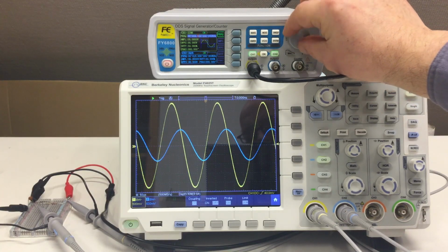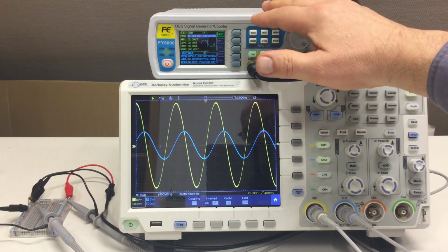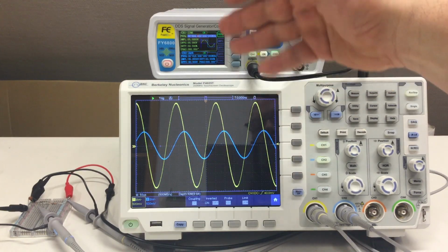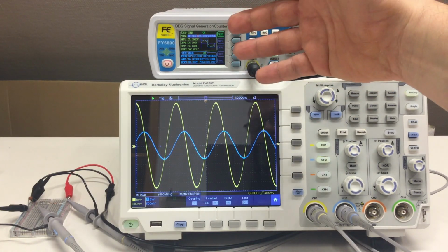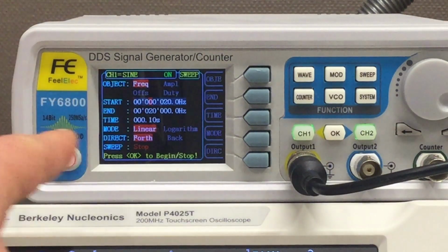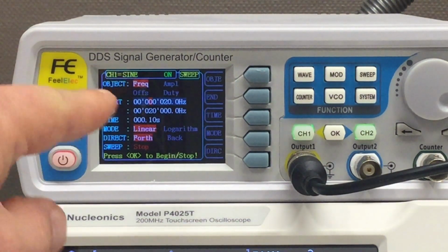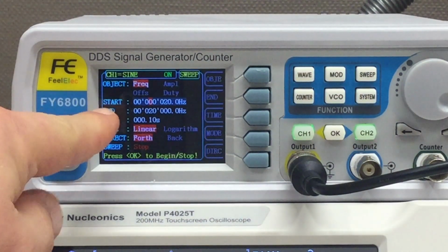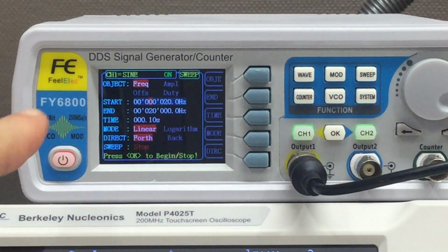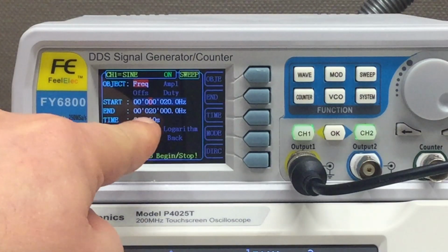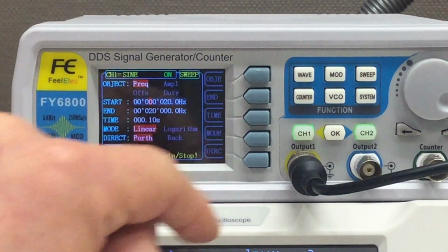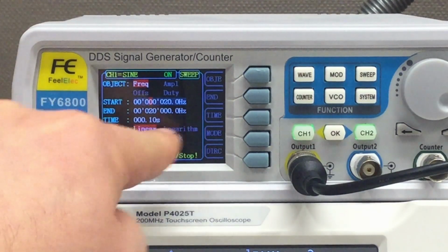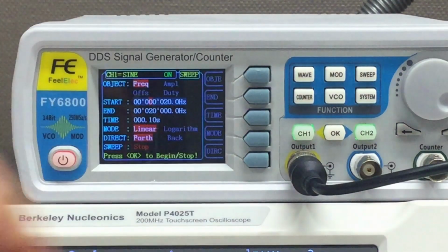So yeah, naturally, most of these generators have something like a frequency sweep, and I will set up a frequency sweep now. I set up here a frequency sweep on the signal generator, with a sweep button. So my start frequency is 20 Hertz. My end frequency is 20 kilohertz. And I do the sweep in 0.1 seconds.